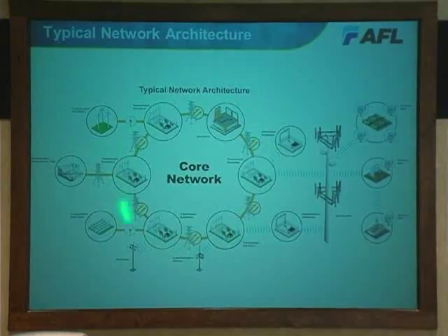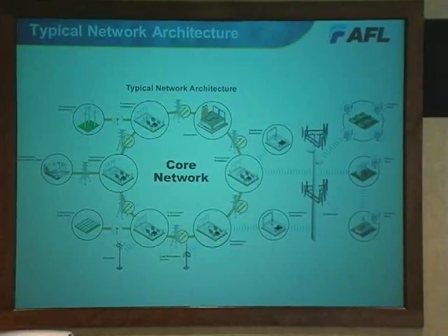A lot of the utilities have an optical network. You've got a ring built out there, and if I put in OPGW, then I've got that fiber into all of my substations because I'm going along the transmission line and I've got my fiber at the substation or at a generating plant. Great, opportunity there to pull that data and send it across the fiber network. But I've got to reach out to those edge devices somehow. This particular example is showing a wireless connection, but somehow I've got to touch all those devices out there and be able to control them and get the data from them.